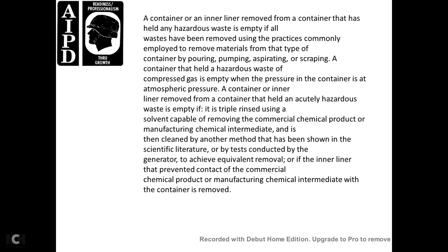A container or inner liner is considered empty when it has held hazardous waste and all the waste has been removed using practices commonly employed to remove that type of material from that type of container, such as pouring, pumping, aspirating, and scraping. For a container that held hazardous waste with compressed gas, it is empty when the pressure in the container is at atmospheric pressure.